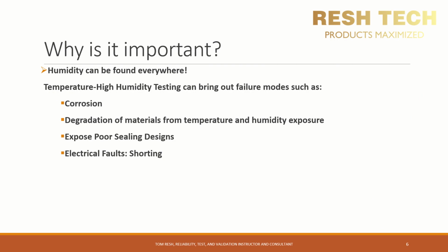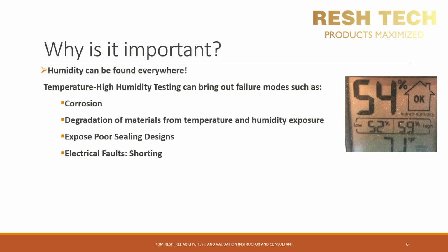So why is humidity testing important? Well, because it's all around us. You may not feel it due to a low dew point, but it's there. If you have one of those digital thermometers, they typically measure relative humidity. To the right is a digital temperature meter that I have in my lab. For me, 71 degrees Fahrenheit or 22 degrees Celsius at 54% relative humidity feels quite comfortable as pictured.